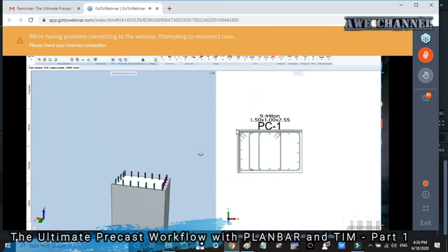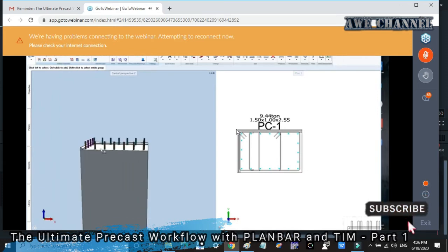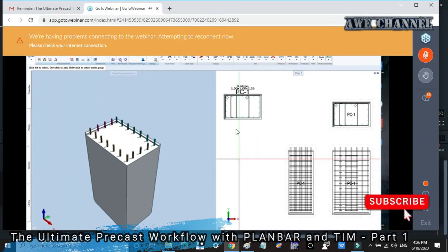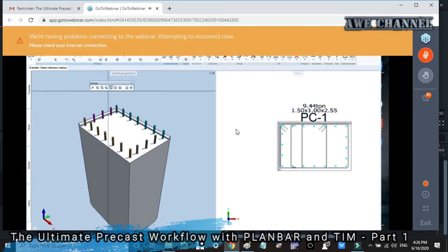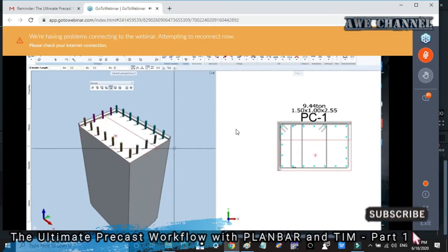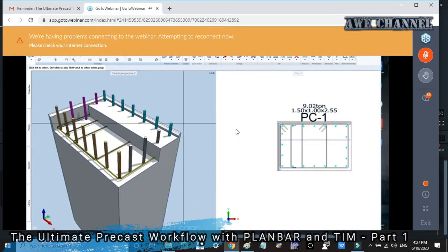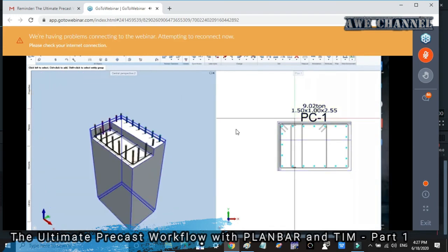So the next thing is maybe, let's say you need to provide a cutout for your slab. Since this one is made from a 3D object, or still a 3D object, you can use the modeling here, and then the extrude. And let's say, for example, I want to have a cutout from this portion up to somewhere maybe here, and a drop of 200. Oops, sorry, it's additional. So maybe I can just cut out again from here, point to point, and it should be on the z-axis, and it should be negative, so it should be 200. So as you can see, you will have a cutout here, and it's still a precast.